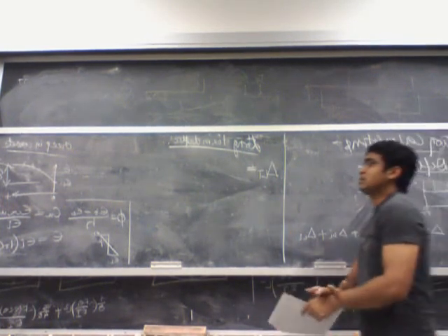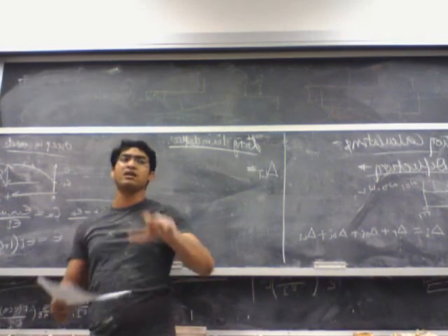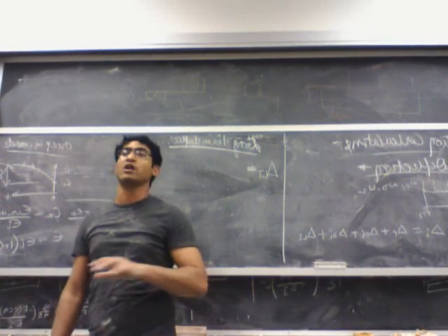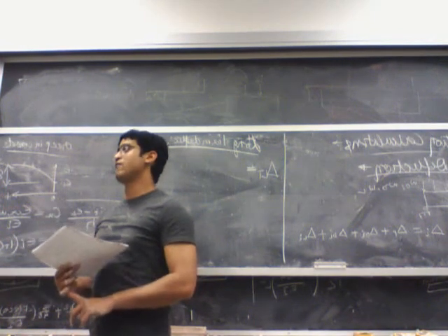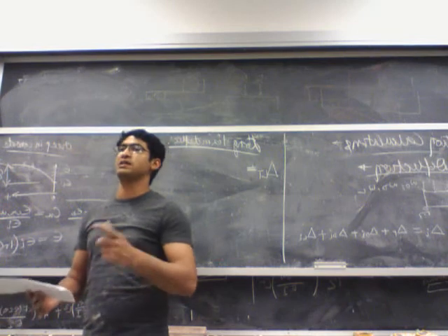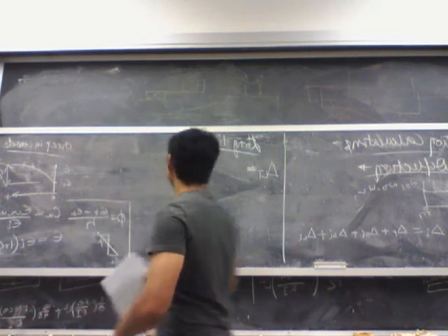the other thing is, creep will only occur for loads which are applied on the system for a very long time. So creep won't occur for a live load, because live load by definition is a load which can be there or cannot be there, right?